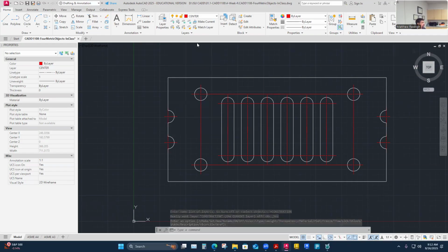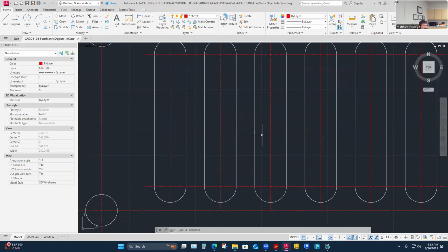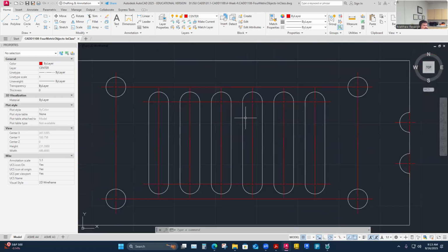Did you figure out, or is it something weird with your center mark? No, I messed up. Having done that now with those center marks, maybe I would just use the center and do lines, because I don't have to use the center marks to do what I'm doing. I tend to use them a lot, but you could do those as center lines too. If I were to do that again, maybe I just want to snap a line across here and snap this line across, and then maybe just snap one line that's the right line and then copy that across. I could have just done this with center lines.